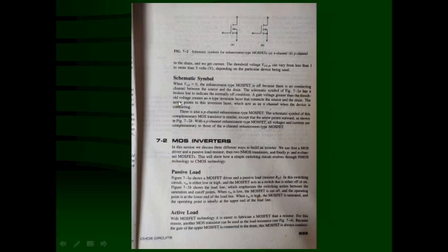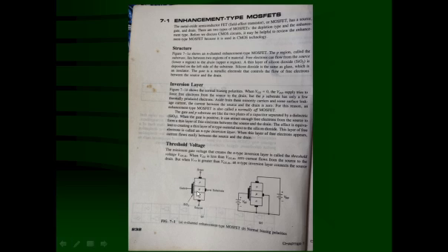Now you can see that there are two symbols here, A and B. This shows that an N channel inversion layer is going to be produced. That's why it is called N channel MOSFET. And similarly, if there are two P-type regions, P and P, and this kind of MOSFET is prepared, then it is called P channel MOSFET, because here the supply is going to be reversed.